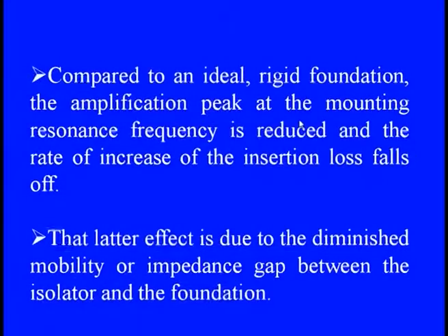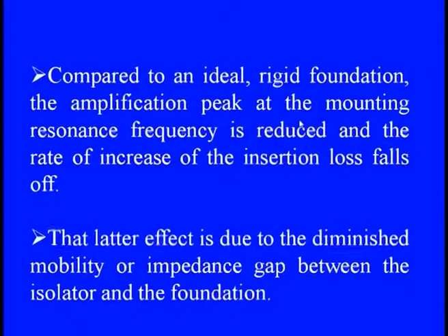So compared to an ideal rigid foundation, an amplification peak at the mounting resonant frequency is drastically reduced, and the rate of increase is also reduced with the same insertion losses, and this is one of the great advantages of this. So when you see the insertion losses being reduced, it is mainly due to diminishing the mobility, or we can say the impedance gap between the isolator and the foundation. So when we say that Yi by Y plate is being reduced, certainly it has a clear impact on the insertion losses.